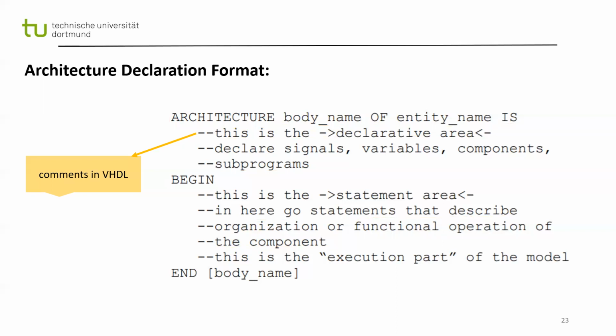This is it for today's video. I would like to thank you for your attention. And what I would like you to do is draw the OR gate circuit using the IEC 60617-12 norm, which I explained in this video, and then write the basic VHDL model and code of the OR gate. So you need to write the entity declaration of the OR gate. You will also need to do the architecture declaration of the OR gate and wrap it all with our design. You can follow the same steps we followed for the AND gate, which should be simple and shouldn't take more than 15 minutes of your time.